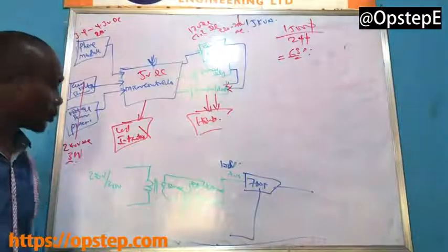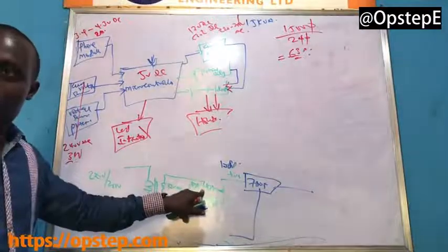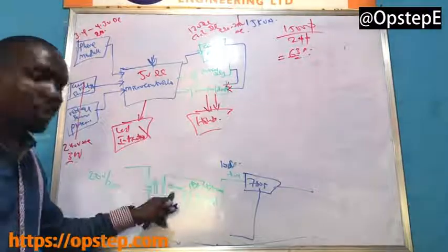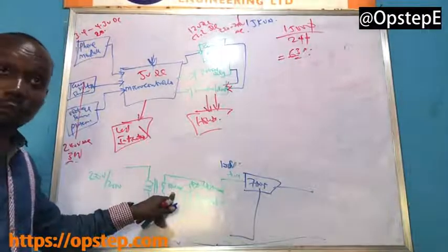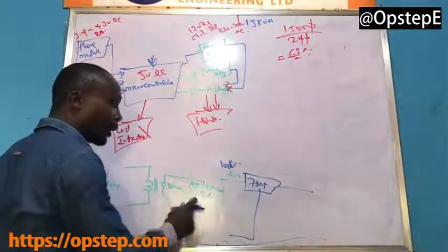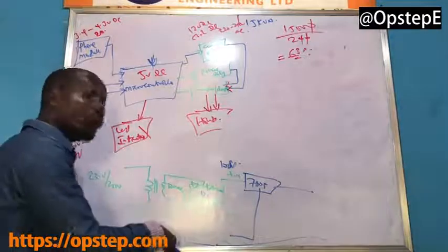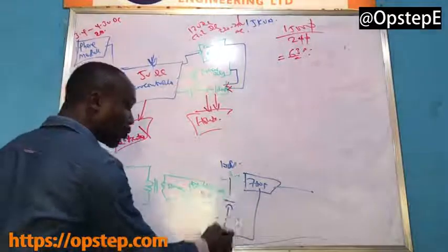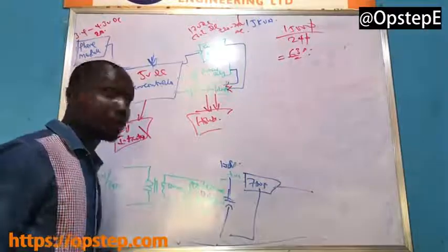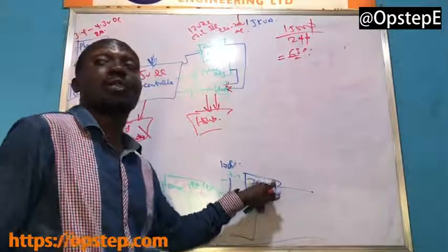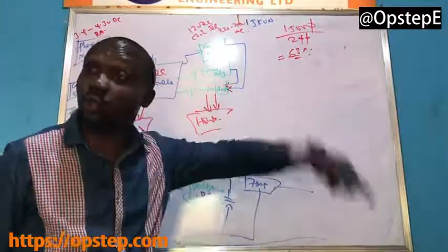We're talking about the voltage sense, yes. A step down transformer to 12 volt AC. The AC is taken to a bridge rectifier and then it rectifies to DC. Even though it's DC with impurities or ripple, you can have a capacitor to help you filter some of the ripple before it's sent into a voltage regulator. That's what the voltage regulator sends to 5 volt. But we can't actually just send 5 volt directly to the controller itself.